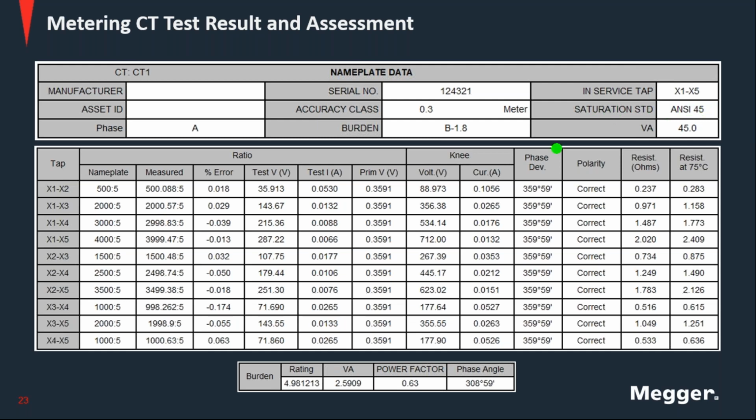Depending on this accuracy class, you could have an IEC standard. So remember, there are different standards. Each instrument transformer will have its own classification, and depending on what standard it was built to, you also need to evaluate against that standard. And that was my reference to the transient transformer. If you have a transient transformer, you need to select IEC for the assessment. This is what determines how this information is going to be used for the calculations of the assessment.